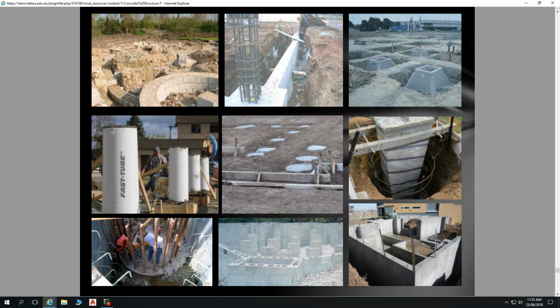But you also have, I can't think of what they're called now. I can't think of the product, but tubes that when you auger piers, you slip these tubes in there and you pour the concrete to give the sides of those piers a very smooth side, so that your earth, as it expands and swells with moisture, can go up past your piers, move past your piers really well.